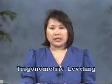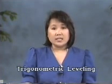Our second method of leveling is trigonometric leveling. This is an indirect vertical measurement method that determines the difference in elevation between 2 points by trigonometric means. Vertical differences in elevations are computed from slope distances, vertical angle measurements, and the instrument and prism heights.